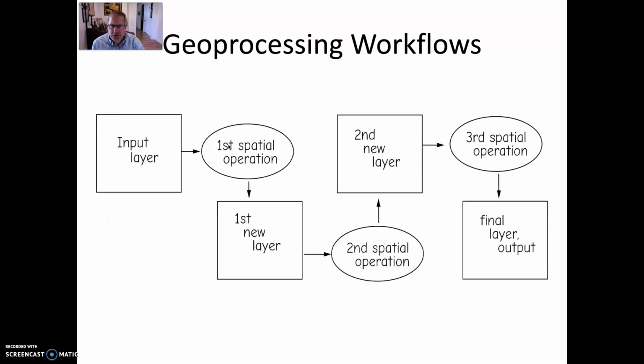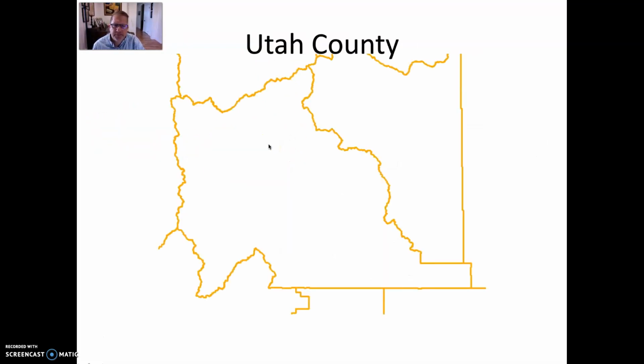So we were talking a little bit about geoprocessing workflows, and a geoprocessing workflow is basically a recipe for solving a problem. It's the way we do design work in geoprocessing and geoanalysis. We take input data layers and then we draw the analysis that's going to happen, then we make a box showing the output data set, the analysis that's going to happen, the final output layer. You can actually have 2 input layers going to a single analysis. For example, with intersect, you might have 2 coming in. Buffer or select would only have 1 data set coming in.